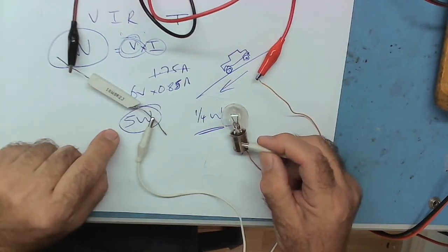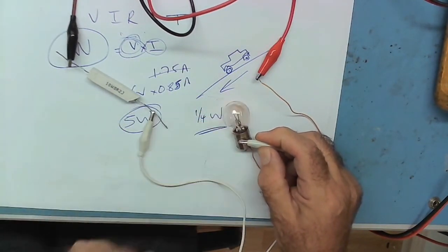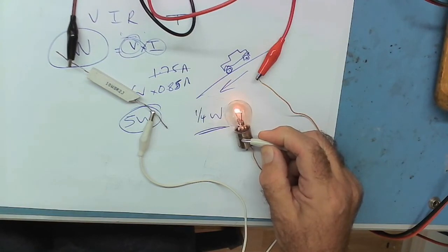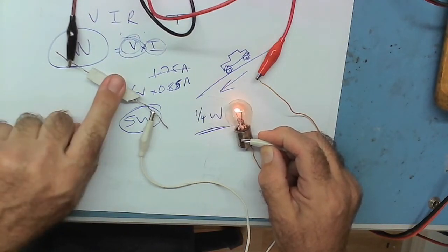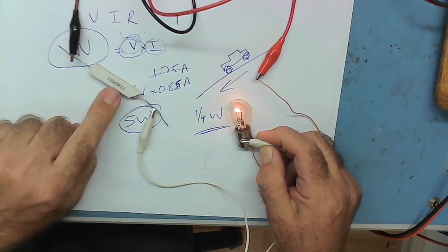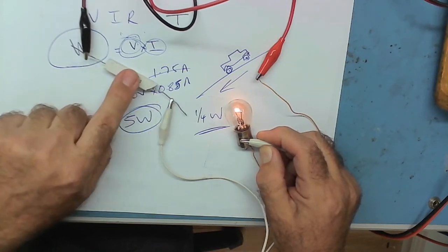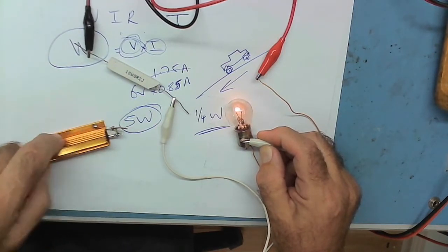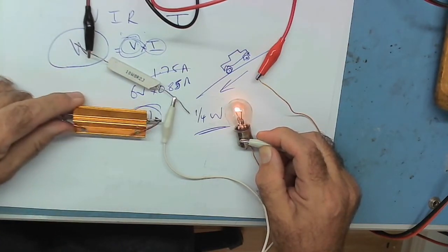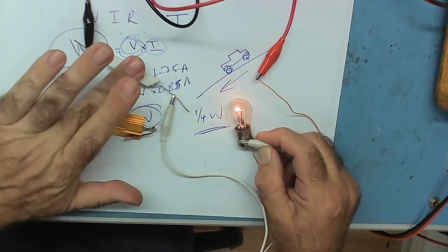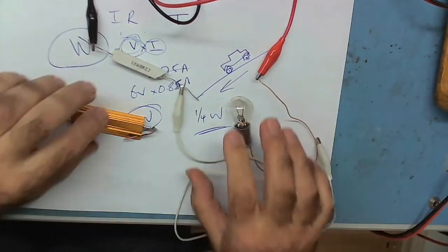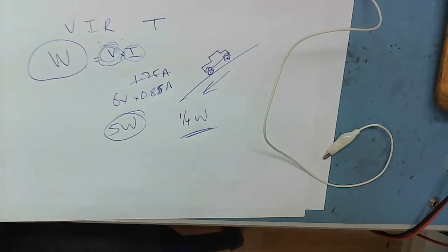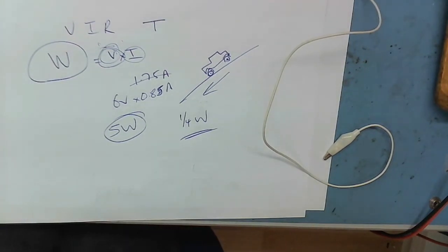And this is our 10 watt resistor. Now what happens? Well, yeah, the light bulb now comes on about half brightness. This is getting warm, but not overly hot because it's designed to handle up to 10 watts, and it's dissipating about 5 watts. This is why things like this have bigger pieces of aluminium that you bolt to a piece of metal, yeah, for 100 watts. That's quite warm now. So that's watts. That's the last thing you really need to know with resistors, voltage and current.